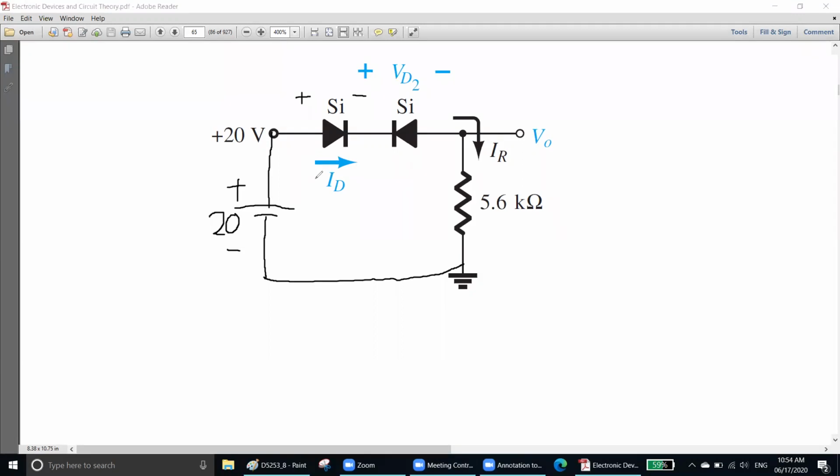In which way the current is going, that will be your plus. Since the current is going in this direction, the first point will be your plus. The current is leaving from here, so this will be your minus. Understood? This one is plus, this one is minus for this diode. For this resistor, this will be plus, this will be minus, because current is going in this direction and leaving from here. So this is the entering point of current, this is the leaving point of the current, that's why it is minus. Now we will apply a KVL.